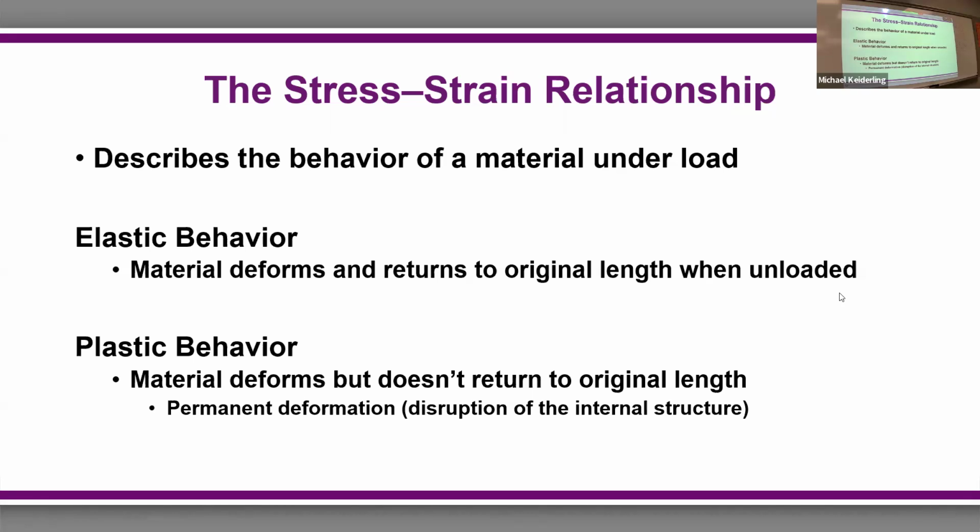And that is where the term plastic comes from. Because plastic is generally something, most of these are thermoplastics. They become plastic and deformable when hot, and you can mold it. So the material deforms, but it doesn't return to its original length. This is a permanent deformation, the disruption of the internal structure.